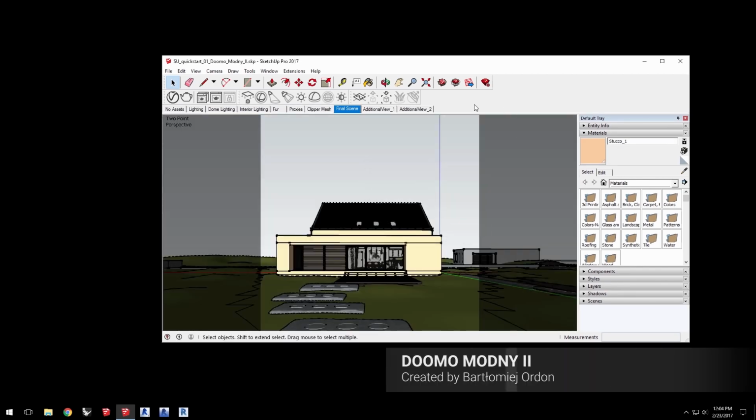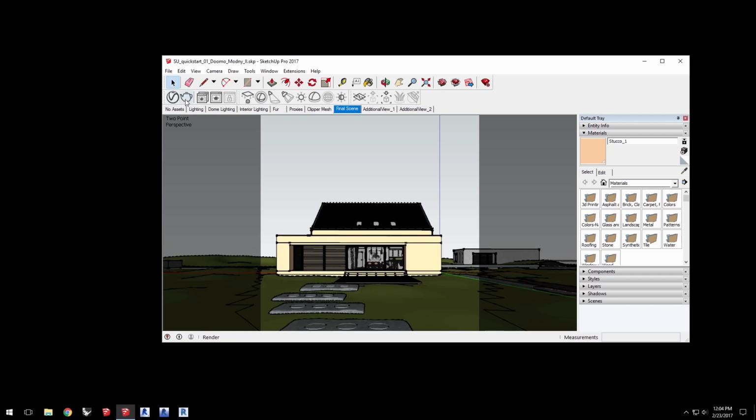When you have V-Ray for SketchUp installed, you'll notice that it has added 3 new toolbars to the interface. This is the main toolbar, which includes the Asset Editor, Render button, and a button for the V-Ray Frame Buffer, also known as the VFB, which is a window that displays your renders. Next to the main toolbar is the Lighting toolbar, which allows you to create and place V-Ray lights in your scene. Next to that is the Geometry toolbar, which gives you access to V-Ray specific geometry like the infinite ground plane, proxies, and fur, for example.